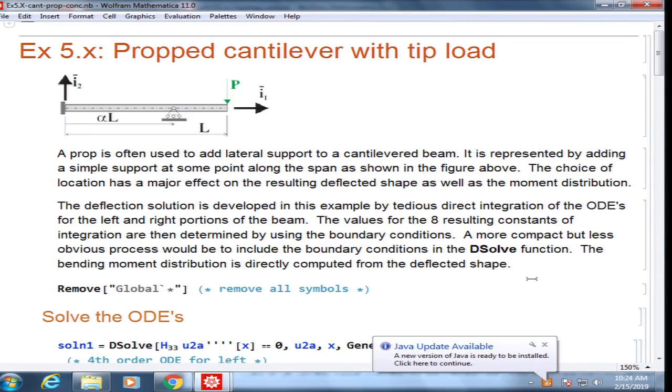I think moment is negative. Moment is negative of this, but because we have a 0 sign there, the negative sign went off. And then the shear force is negative of moment. So dM over dx1 is equal to minus V. So I think it's correct.